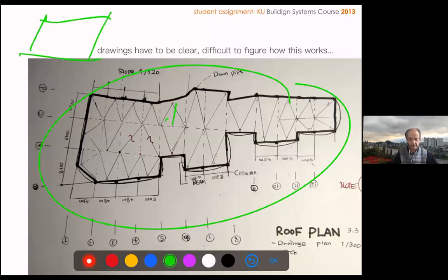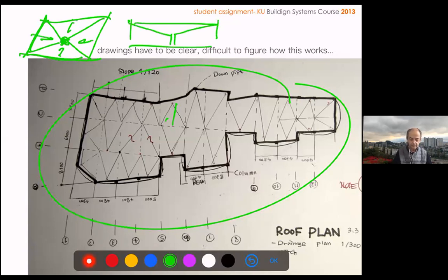So if you have a square element, you may have a trench in the center, so you will give some slope in each area. It's like an inverted roof, right? And usually you will have this kind of inverted pyramid. If we make the section, we will see those sides and the front, right? So the section will be like this, right? Taller on the borders and lower in the center.